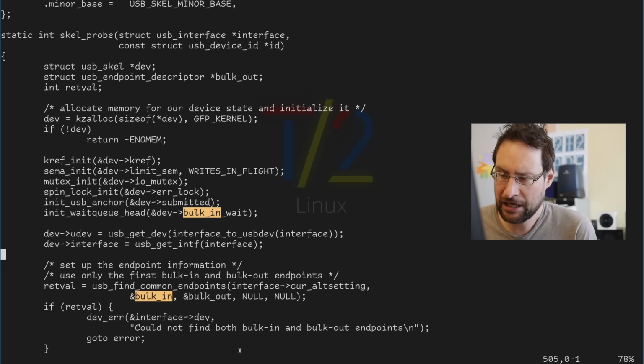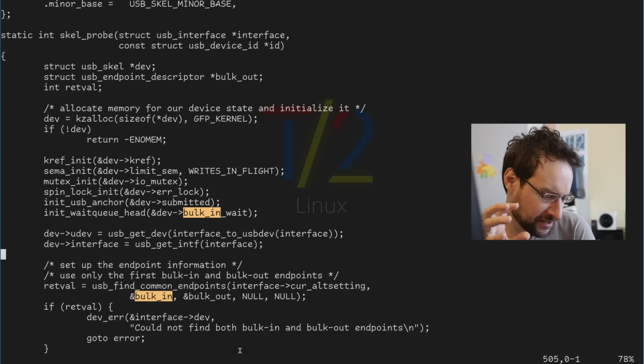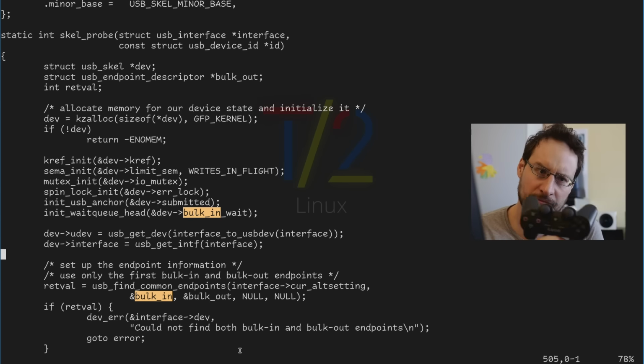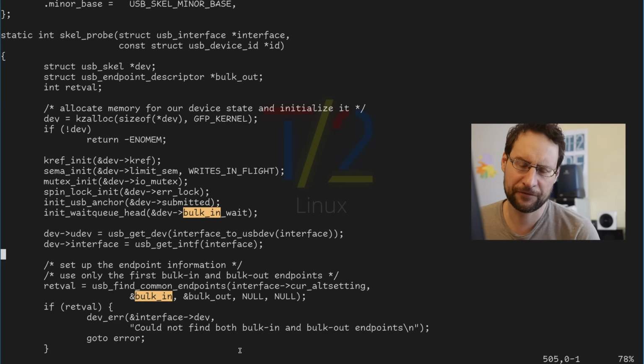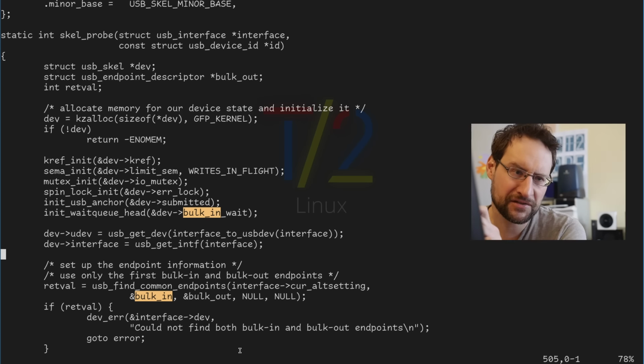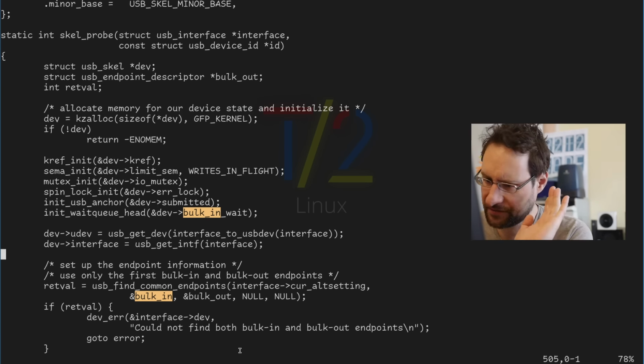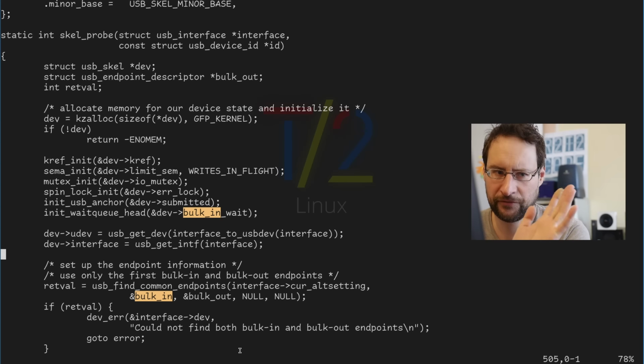It might need a USB set configuration, because what this does is USB devices can have multiple configurations, like gamepads, keyboards. Probably, I didn't check, but maybe keyboards have 2 configurations, like simple boot protocol and more fancy stuff. And even audio devices can have configurations like a simple audio config and an audiophile audio config.